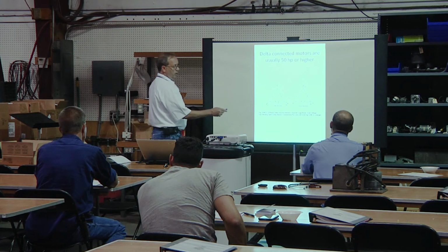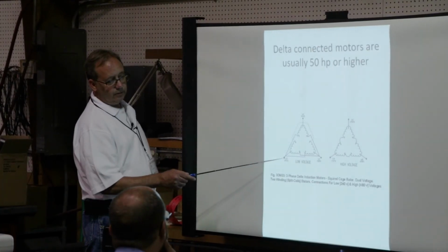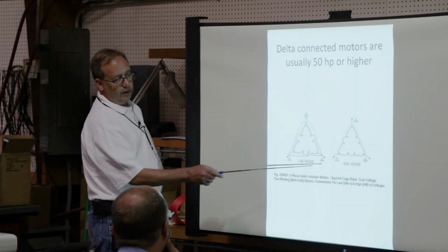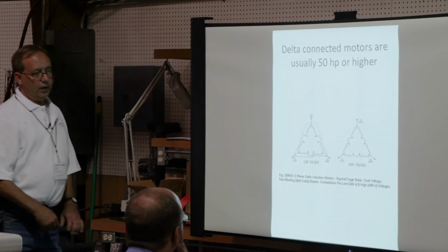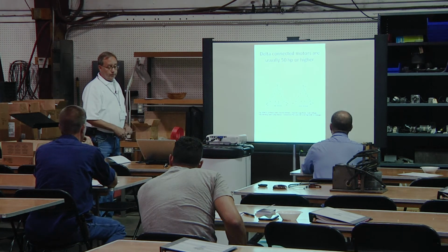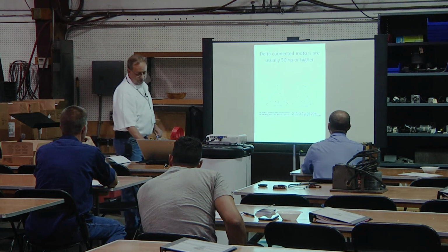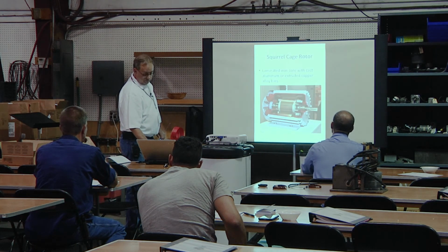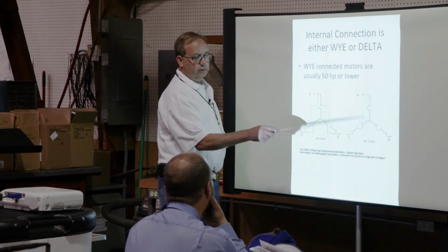So this shows the low voltage connection, which is essentially a parallel connection, while this is a series connection. You'll see a lot of particularly foreign motors, they'll bring all 12 leads out. So what they're doing, like this one, is they'll bring their neutral point out externally.